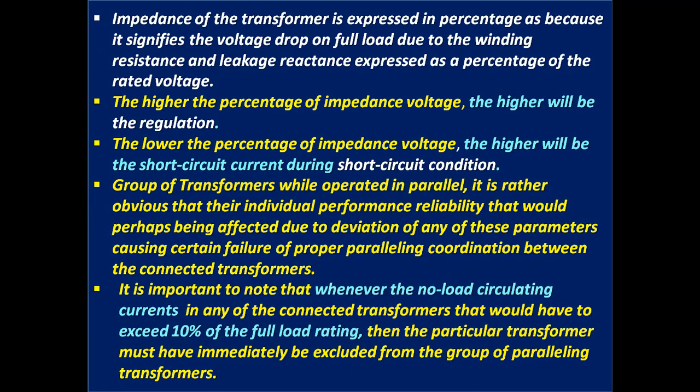Impedance of the transformer is expressed in percentage because it signifies the voltage drop on full load due to the winding resistance and leakage reactance, expressed as a percentage of the rated voltage.